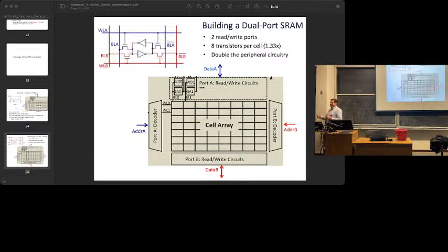If you instantiate a memory block, you can go into the IP cores in the vendor tools, like Quartus or Vivado, and you can say, I want a memory block, like this logical memory. If you instantiate a logical memory, one of the advanced parameters you can set is what happens in that case. The RAM itself has some natural behavior. I think the natural behavior is we don't know. So if you want the fastest timing, you actually say, I don't care. I'll never do that. I don't care what happens.